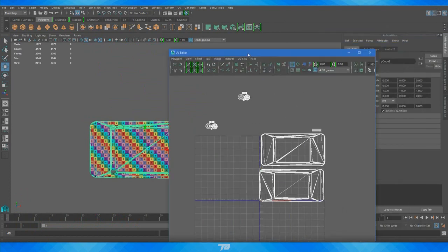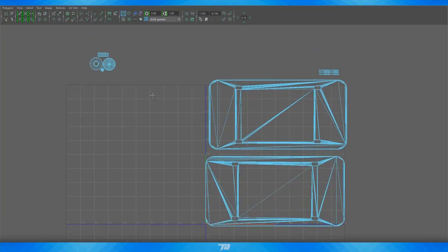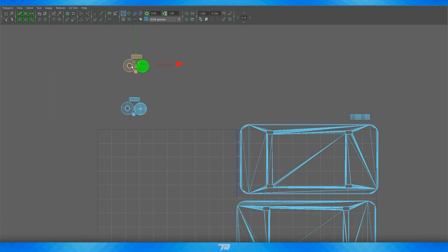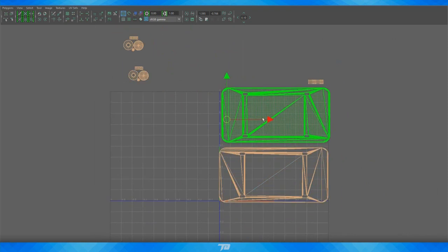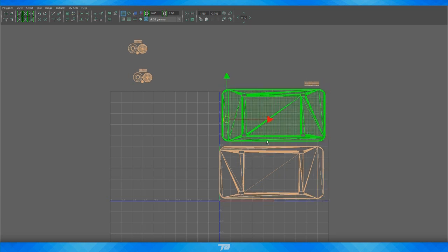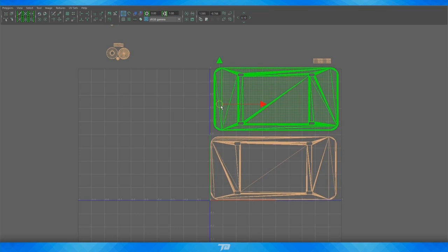Everything's UV'd. We just got to put things into the correct spot in our UV sheet, which is pretty straightforward and pretty easy. We just want to maximize the space in our UV sheet here. So I'm going to have everything selected when I do this, just because if I'm resizing one thing, I want to resize everything to scale. So let's just try and pack this in as tight as possible.